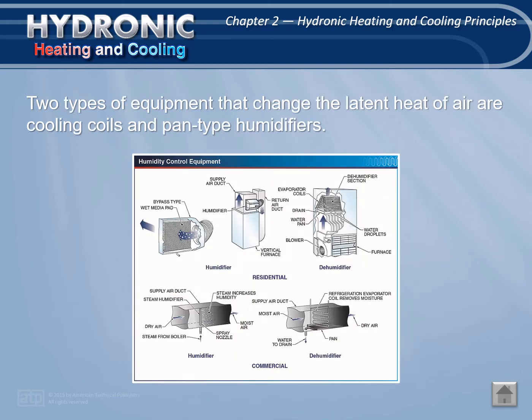Humidity control is normally not a function of a hydronic heating system. When heating, it may be desirable to add moisture or to humidify the air to prevent the moisture content from being too low. This can be done with a separate humidifier. In cooling conditions, one of the functions of the cooling system is to reduce indoor humidity until a feeling of comfort is established.